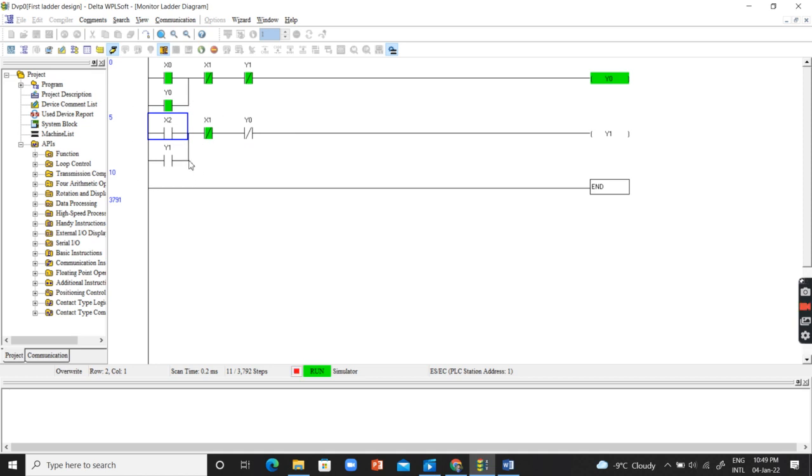So the only way you can turn this motor in the other direction is that for this power button, which is a single contact, you first need to make sure that power is disconnected, right? Once the power is disconnected, and you power on the circuit again, then if you apply the push button in the second input, it will allow the motor to turn in the anti-clockwise direction.